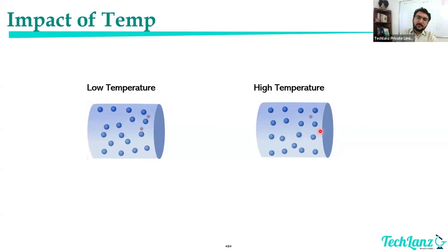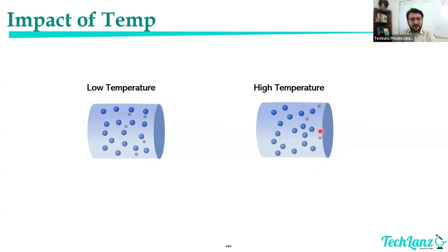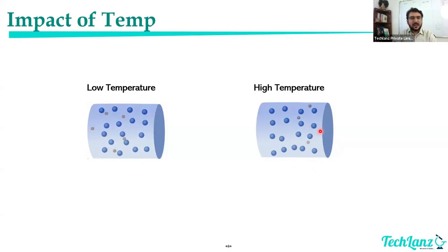At sub-zero temperatures, the electrolyte almost freezes, right? The viscosity and density become so high that it does not promote the movement of ions and electrons inside the electrolyte, and the chemical reactions also do not happen. So this is the reason why the capacity increases when the temperature is higher.